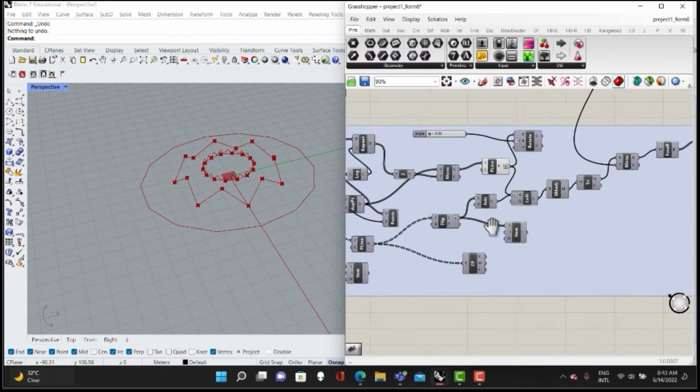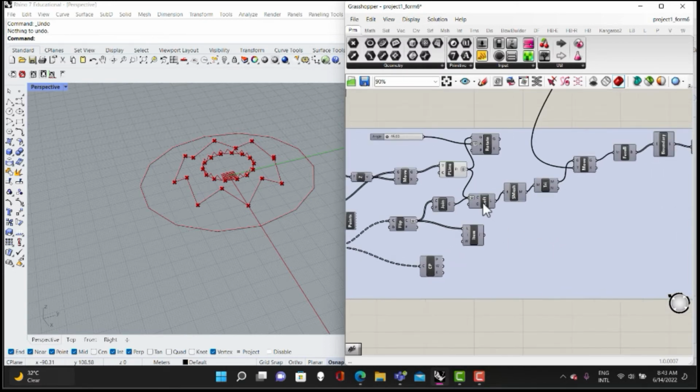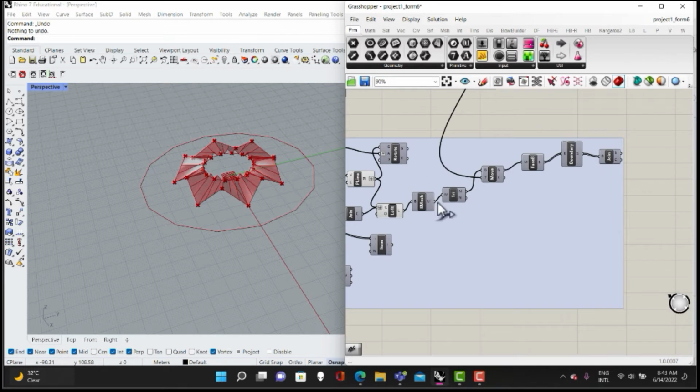And from the polyline, I was further able to enhance the shape by creating a loft, and this loft actually constructed the segmented shape of the top roof. And then the final form came from triangulating the simple mesh and having it all joined together and moved up.